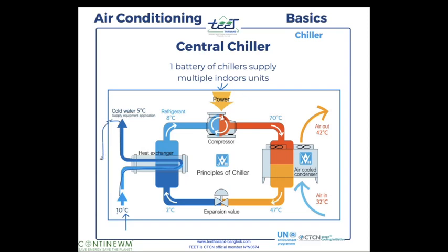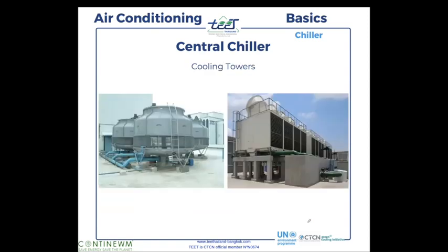So the water gets cooled and gets back to the AHU inside the room. Here we have the room, the AHU, and the water gets cold and gets back here to the chiller to get cooled, okay? And then we have the cycle, how to cool the water from the chiller with the compressor. The heat is transferred to the water, and the water is cooled with the air, the cooling tower. This is what a cooling tower looks like.